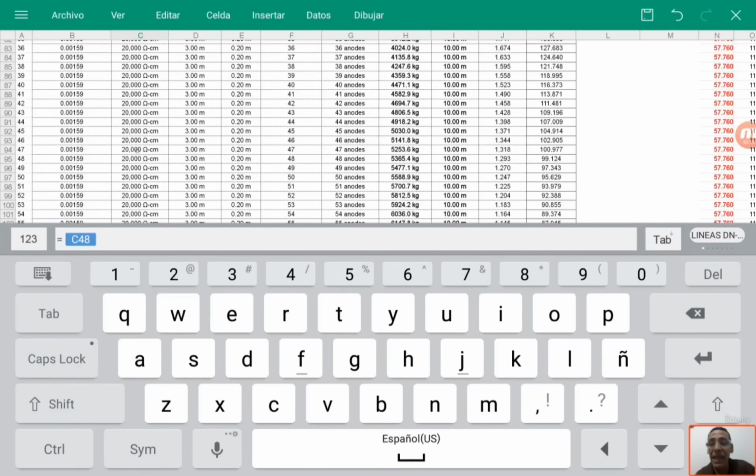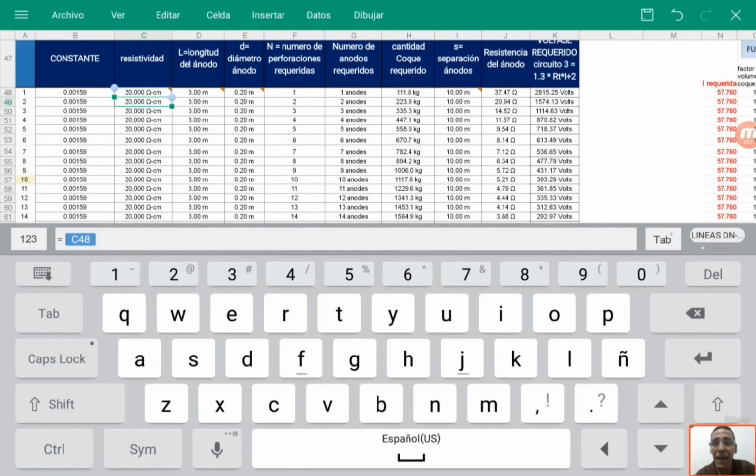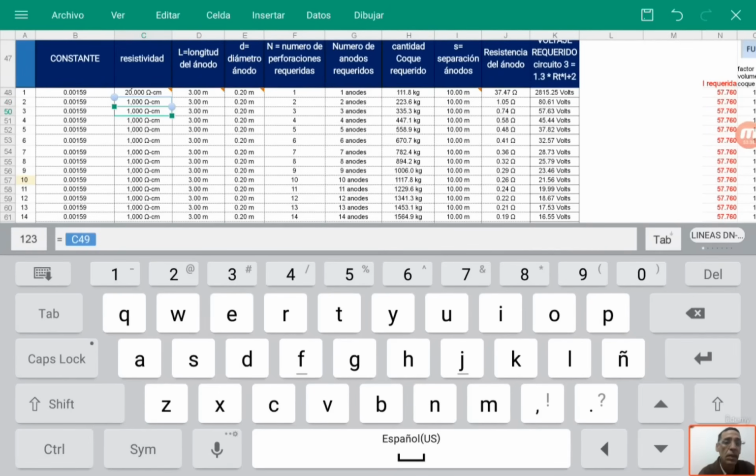Did you notice that this value messed up everything for me? The whole calculation and the design? If this is the real resistivity, 20,000, but out of laziness, negligence, or incompetence, I left it at 1,000 because that's what they told me, the system won't work when I install, build, and start up the system. The system didn't work, of course, because you had a false resistivity.